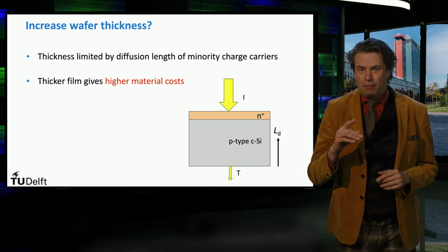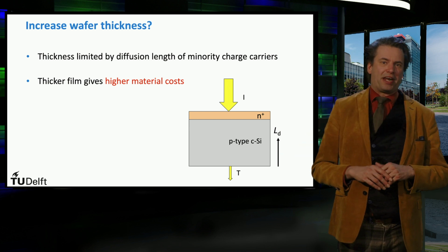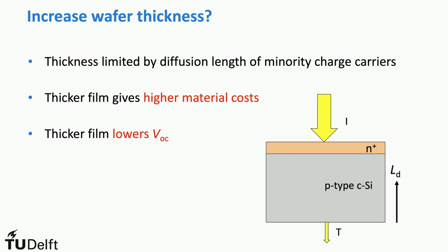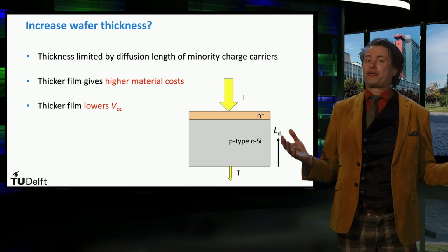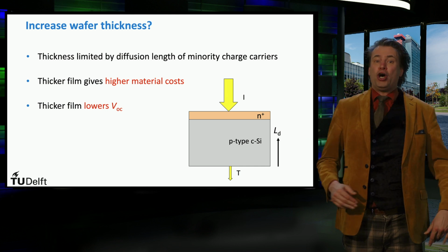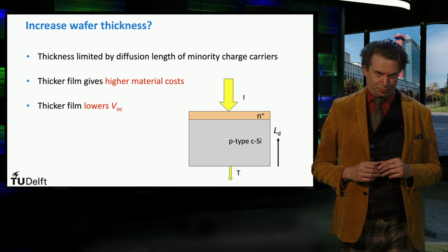In fact, 1 mm of silicon will absorb virtually all photons up to the band gap of silicon. However, the maximum thickness of the wafer is limited by the diffusion length of the electrons in the p-type silicon, as these electrons need to travel from the point of generation all the way to the front surface. It would not make sense to generate electron hole pairs close to the back surface when the electrons will likely not even reach the p-n junction at the front.